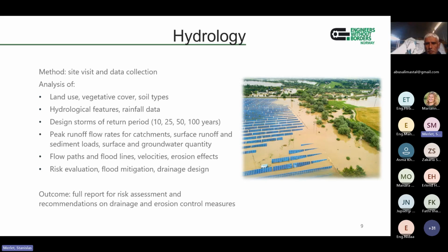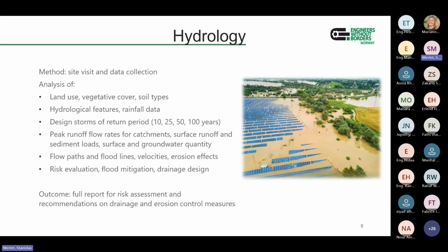Yeah. What about extra consideration due to dust and how to clear the panels to get maximum power? Very good point also. So these are the site study very much related to the site, but again, a checklist for sites choice or decision would definitely include dust situation to avoid what we call the soiling.